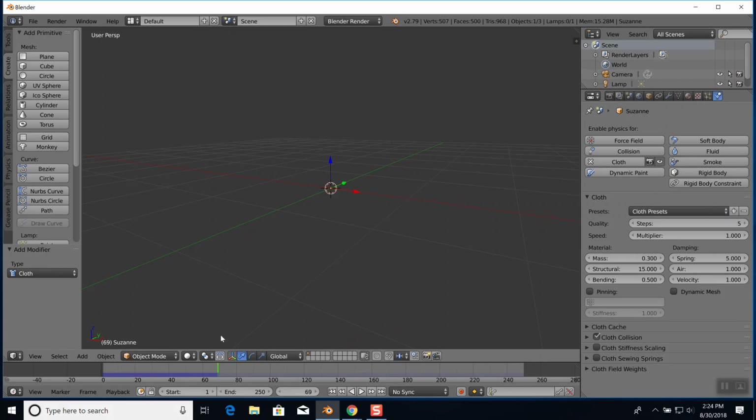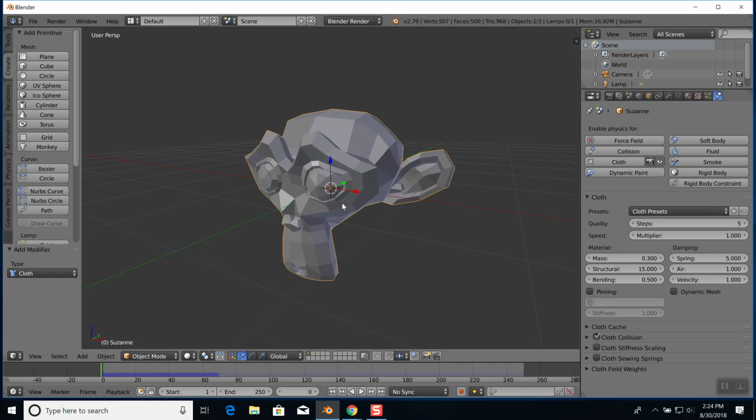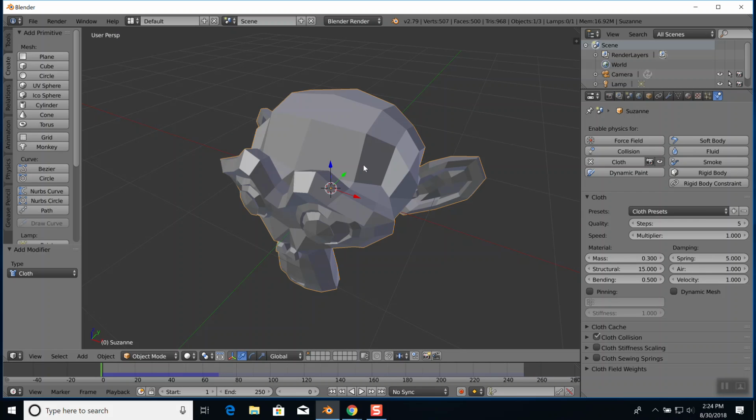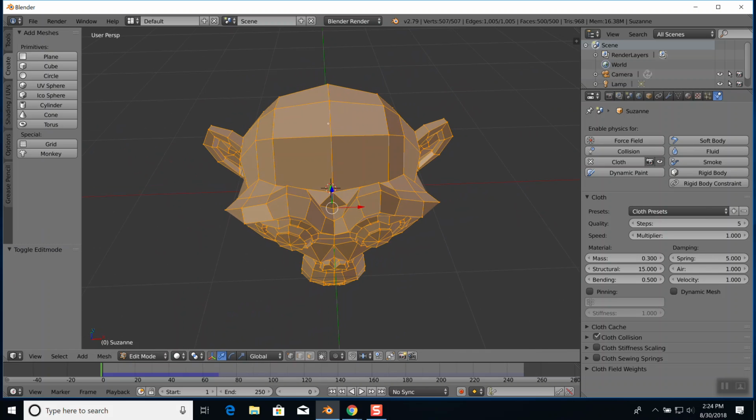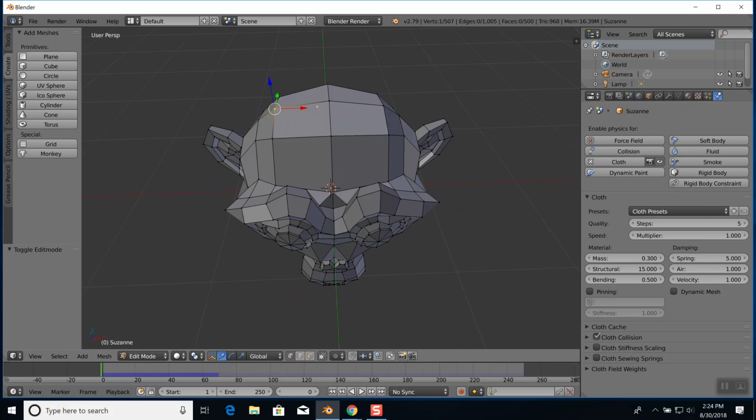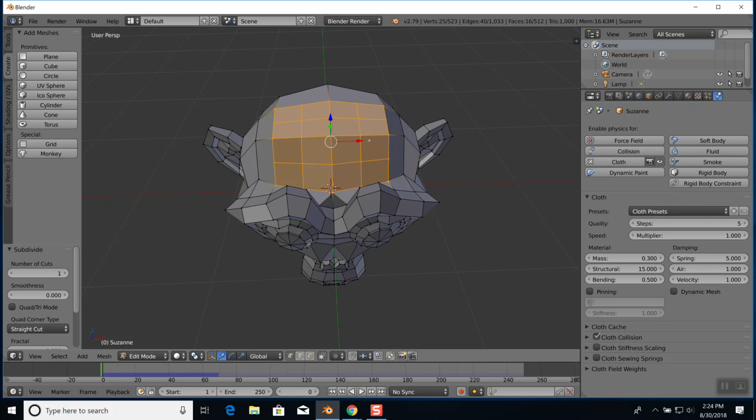So let's go add a vertex group. So the monkey's pinned. So I'm going to go in my edit mode. I don't have many vertices up here, do I? So if I want to create some more, remember you can subdivide. I'm going to make sure I don't have everything selected though, because I don't necessarily want a bunch of vertices. But I'm choosing those ones up there, and I do a W for subdivide. And I got more here. Let me do one more subdivide. That's probably good enough. Again, it'd be overkill probably to do it on the rest. Just doing it on those.